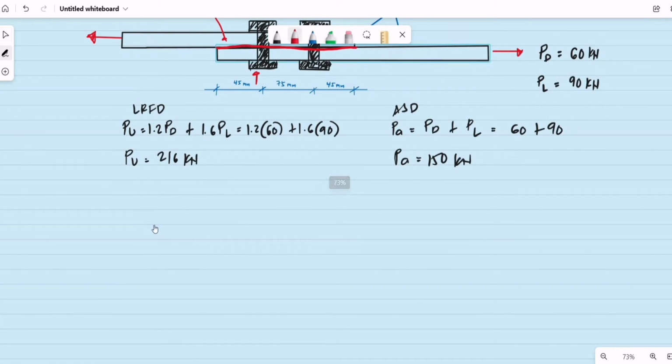From our reference a while ago, we have the value of R sub n equal to mu, basically our coefficient of friction, multiplied by D sub U, multiplied by H sub F, then T sub B, then N sub S. So the value of mu is equal to 0.30, this is for class A. And a while ago, the value of our D sub U is equal to 1.13.